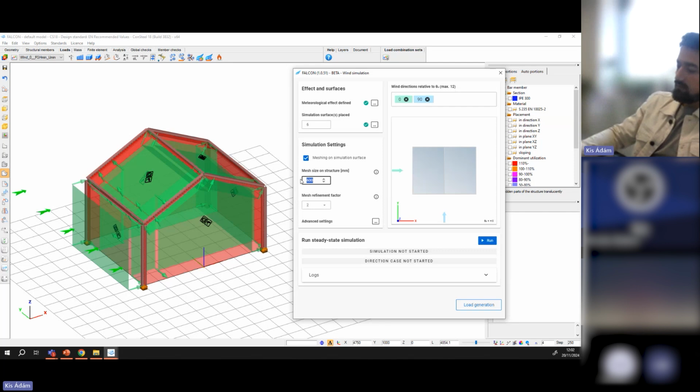But obviously we can change it, and it is recommended when you are at the beginning, because I really think of simulation, or CFD in general, as an iterative process. The results can be obtained really fast if we have a large mesh and a small domain, and it is quite easy to calculate.